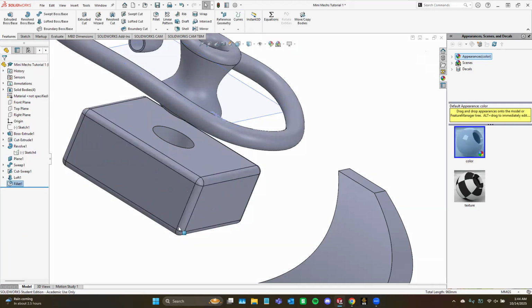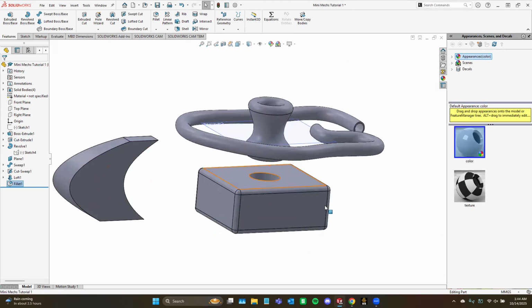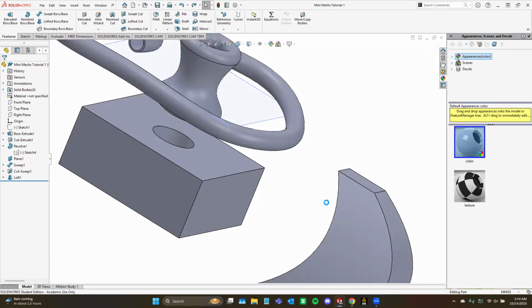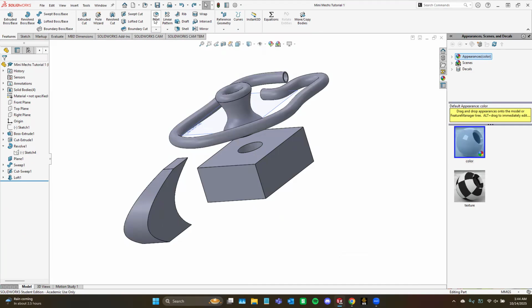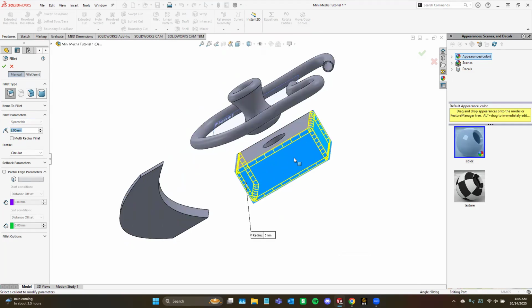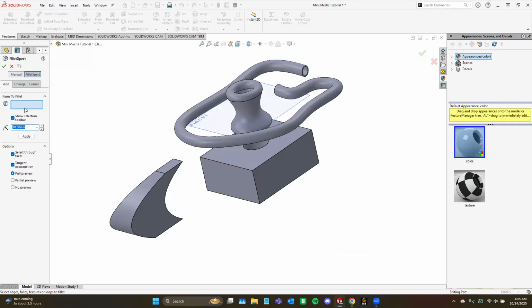So you can either manually input those fillets, or just Control Z real quick and do that. With a manual, you can also click on faces, which is probably easier to do. But there's also a fillet expert. When you click on an edge, you'll get a little bar there with different options.